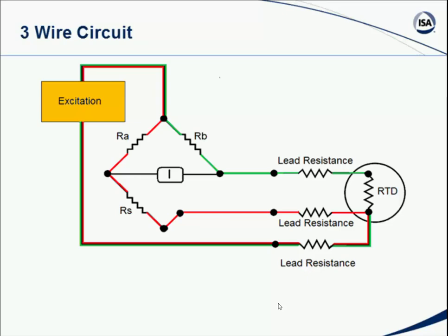In most applications, we will see either two or three-wire RTDs. You can use a two-wire RTD very effectively as long as the RTD is mounted very close to the measurement device. And in many cases these days you can buy RTDs where right in the RTD mounting head there is a transmitter device that will convert the resistance of the RTD. It will measure right there, which means that the leads for the RTD are, we're talking about inches, and therefore there's not much of a correction that needs to be made. On the other hand, in older applications, we'd see three-wire signals coming back to a measurement device that's a bit further away, and that can make our correction for us.